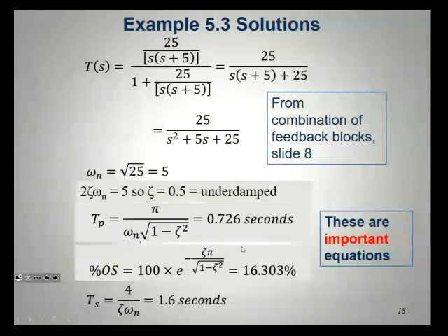Yeah, that's about it, really. Anything else I would like to tell you about that? I think. Yeah, this is sometimes referred to as an open loop transfer function because it's like the equivalent open loop transfer function of the combined G and H transfer functions. So just be aware of that in the book. Sometimes when you're going through it, it talks about open loop transfer functions or equivalent open loop transfer functions, but that's referring to this T bracket set.